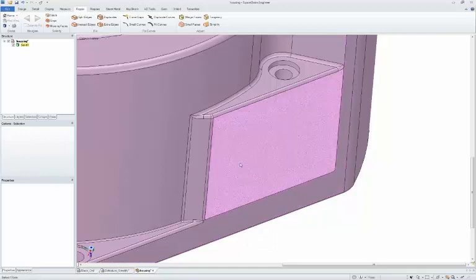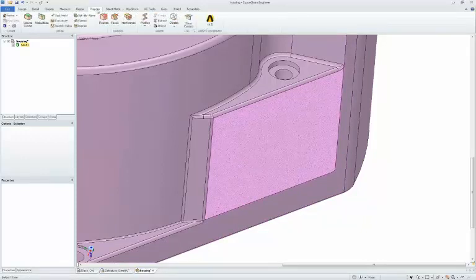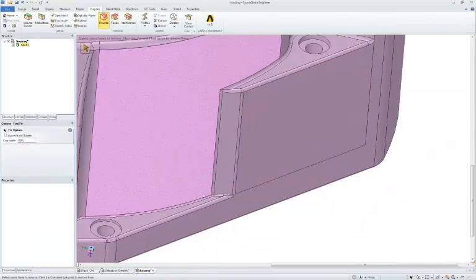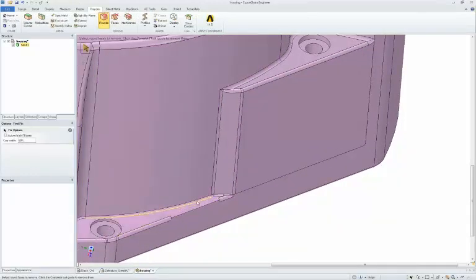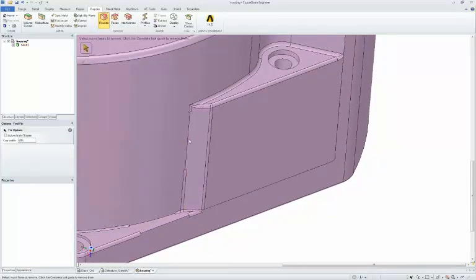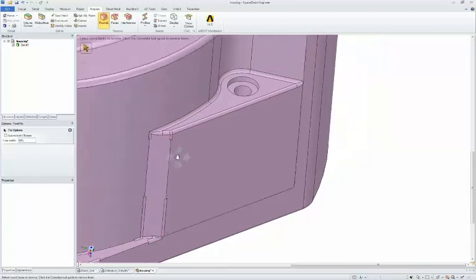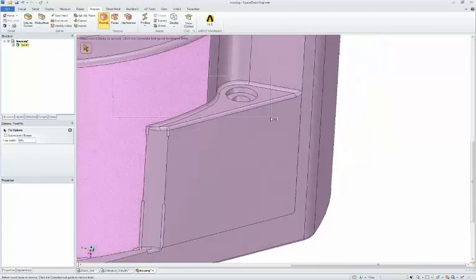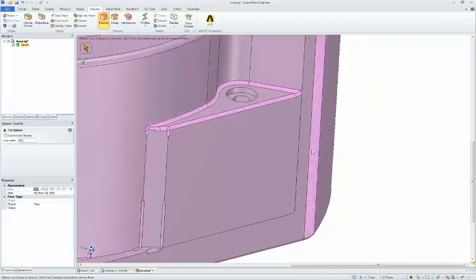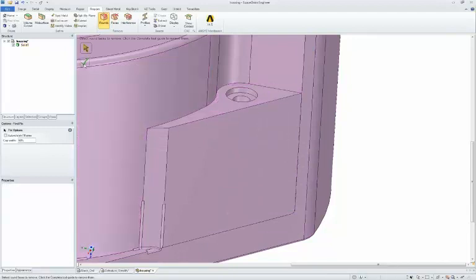If you get almost a mistake that's there, don't worry about it. SpaceClaim lets you, again, clip rounds, like I was showing you before, to remove a section of a round or a model. Notice how you can just start to clip these to remove sections you don't want. And you can actually box select to grab just rounds you might want to remove and eliminate.